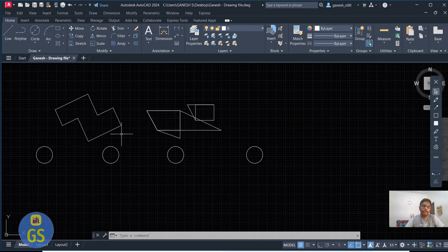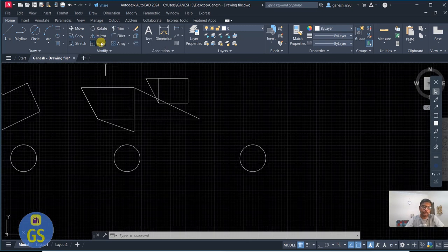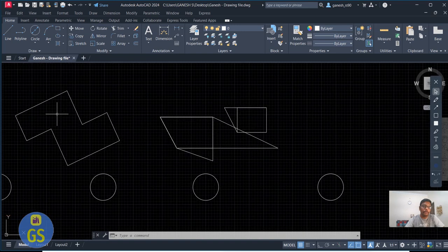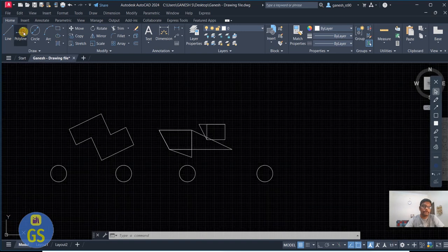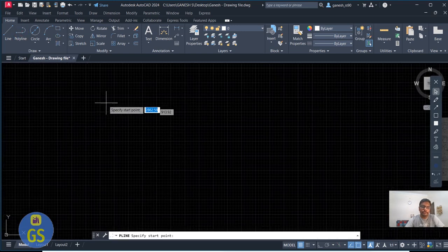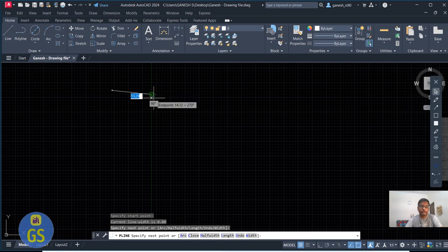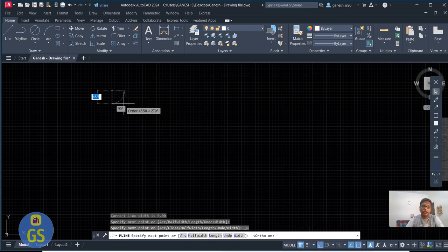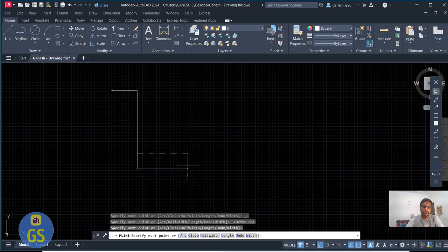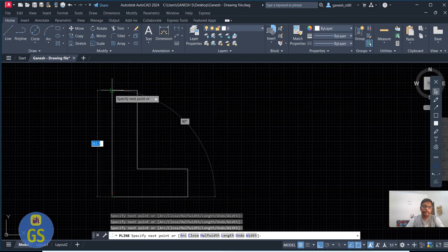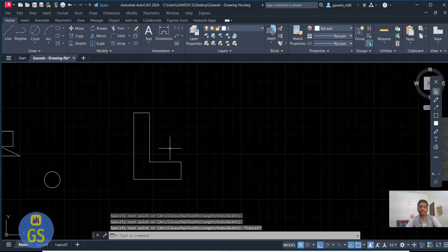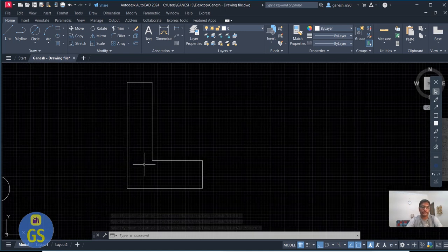In the same way, you want to do some mirror objects. So I want to do the mirror of this. Let me show you here. For mirror objects, let me put ortho on, with a similar kind of image. Okay, so now I want to mirror this. Similarly, I want to make a sketch here with the same dimensions. Whatever I have done with the same dimension, I want to do the mirror of it.